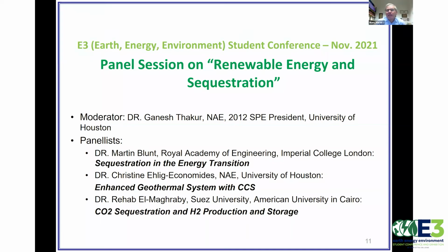Okay, I think we have lots of experience with CO2 injection for enhanced oil recovery. So there isn't a unique challenge. The principal challenge with injection is to make sure that you don't fracture the formation, because that could lead to potential leakage of the CO2. So it's really the pressure monitoring, but again, it's using the same skills and experience in the oil industry. Fantastic. Very good answer.